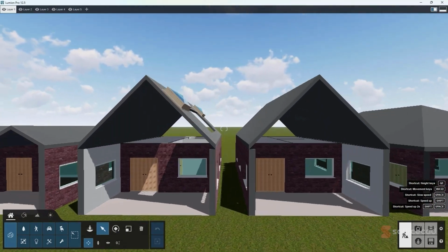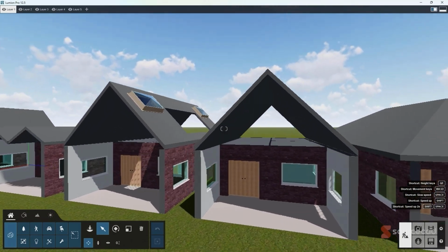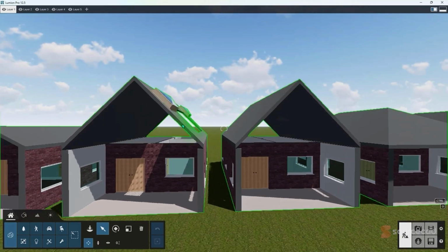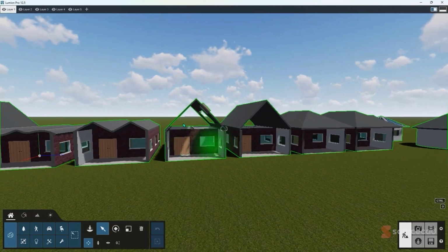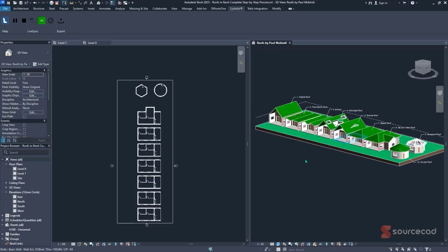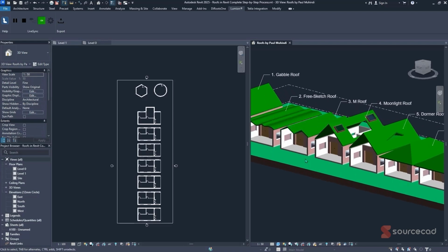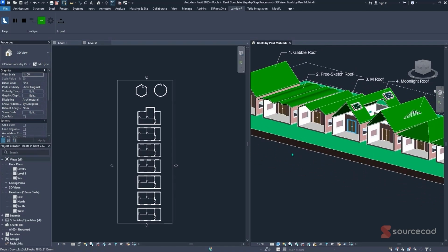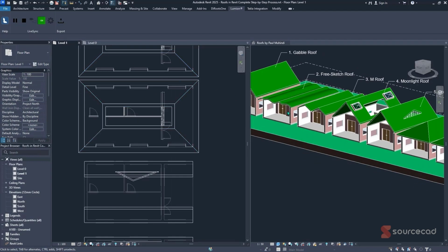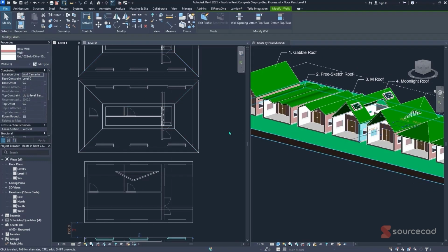So you can obviously play around with the materials that we have worked with. So over here, we did not attach these specific walls to the top of the roof. That's why we have here this look, but it can be easily done still within Revit, and it's going to be updated. So all that you have to do is just simply dash select all the walls that you have. So for this case, this is the specific area that we have this issue.